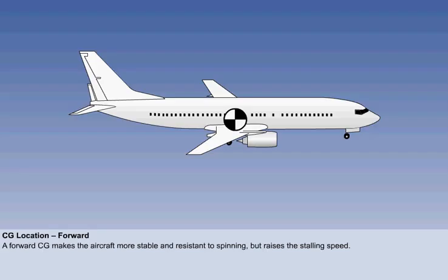Within the loading of the aircraft, the centre of gravity is more significant than the mass itself, as it affects the aircraft's resistance to spinning, as well as its behaviour in the spin. A CG near the forward limit makes the aircraft more stable, with higher control forces, which make it less likely for the pilot to make large, abrupt control movements.